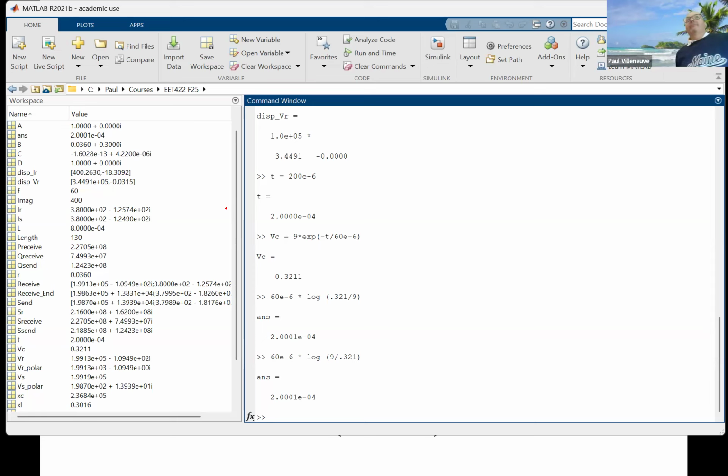I didn't actually teach them how to calculate charge and discharge, but that's what we basically explain, which is you ramp it up and you ramp it down, and how long it takes to charge is when that flasher circuit. So the whole timing on a 555 timer is based on how quickly that capacitor charges up to a certain threshold voltage to turn the output either on or off. That's all it is.